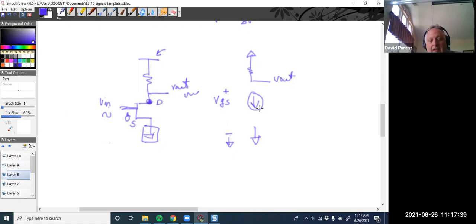This is the drain, and the way you draw these is that would be the drain, that would be the source. And as drawn, ideally, there's no connection here, right? But there's actually feedback capacitances and even resistances. So what is this current? Well, it's VGS GM, right? The GM converts a voltage to a current, and you're getting this from your DC. Now, this might look a little hard, so you redraw it.